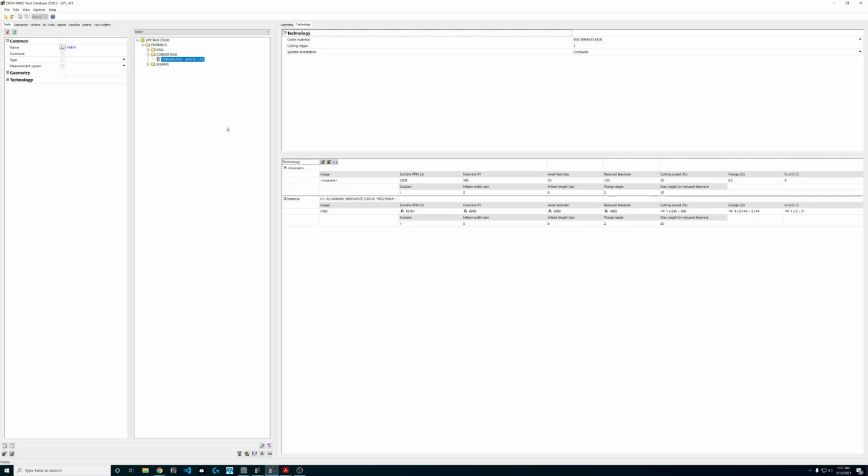And now, whenever we're high speed machining, guess what? We just turned on coolant and the chip conveyor at the same time because we know we're going to have a lot of chips. Oh, you know the code for your mist extractor. Let's make sure that anytime we turn on through coolant that the mist extractor also turns on. It's as simple as defining those generic numbers and then tying those numbers to M codes in the hyperMILL post. Super powerful. Back to HSM.